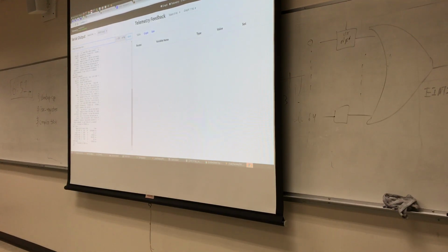When you are not connected, you can choose your baud rate. I have all the default typical ones you would see. You can change the frequency at which you want this thing to refresh. These are just ways to make sure your CPU is not using up too much memory or too much CPU. Usually 5 Hertz is fast enough. And reconnect. It'll restart every single time you connect it, just so you know.